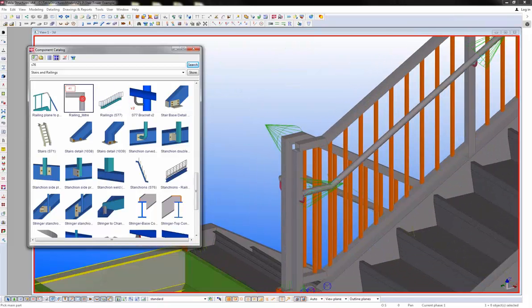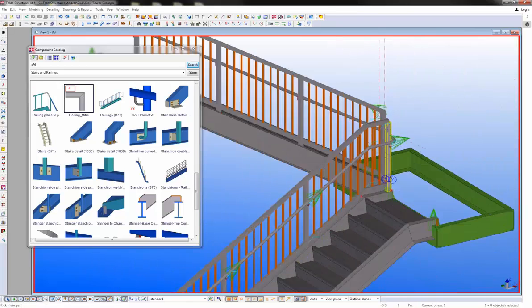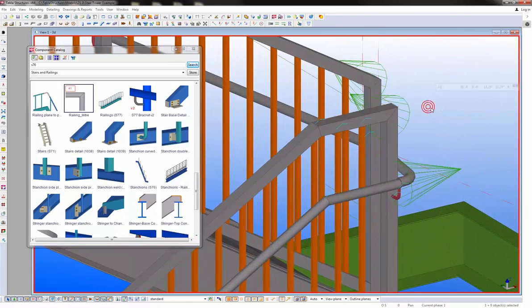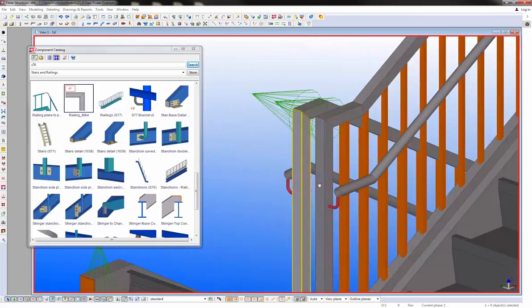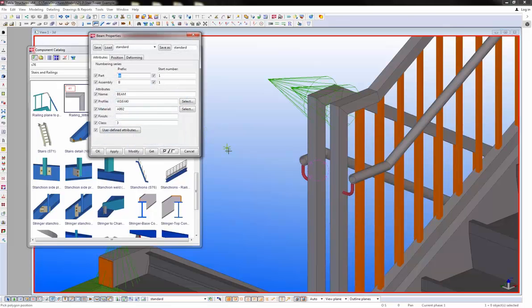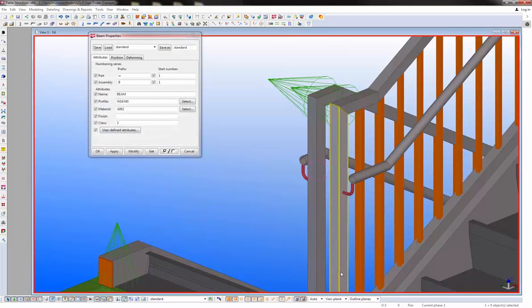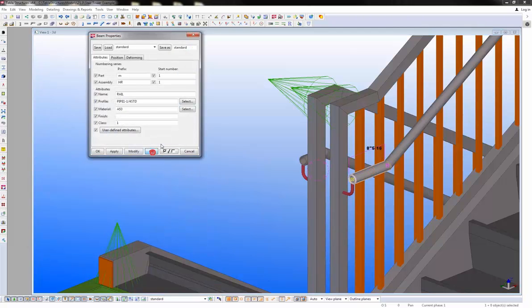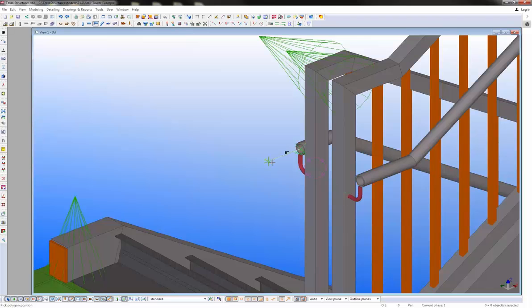Then I'll just add some of my finishing touches. Putting my miters on the ends. And then I can add a return like I did at the lower section. So again, I'll open up my polybeam tool. I'll simply go ahead and take the properties from one of the current grab rails. It's very easy for me to just throw this in.